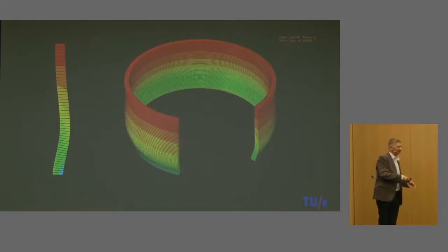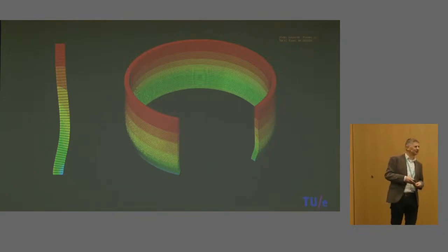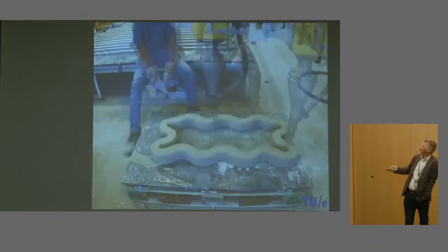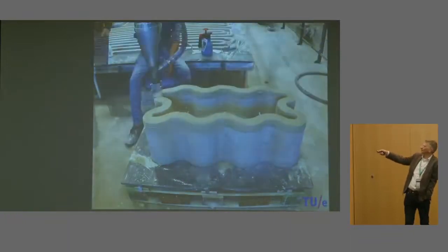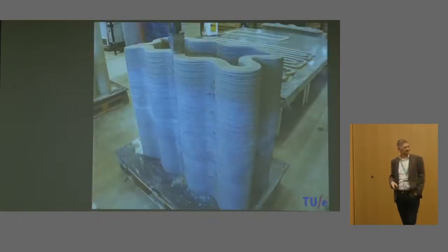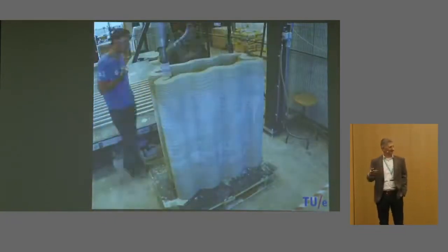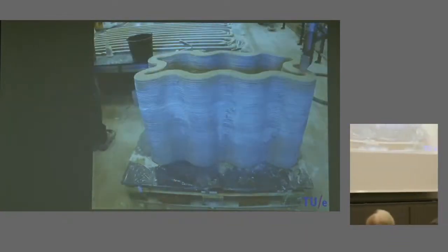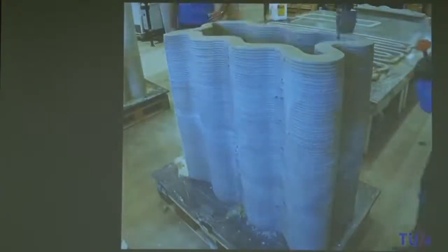And that's the funny part, because now I can play with my concrete, which is really an advanced type of concrete, these printable concretes, but I can also play as an architect, as a structural engineer, with shapes to prevent the buckling of this. And once you understand the whole phenomenon, you can just print. Now, of course, I made use of the knowledge. I printed the wall with a series of curves that's much more stable in terms of structural stability, and then you can print as high as you want. So if you know the trick, you can just print. You can print fast, and then you're in control of what you're doing.